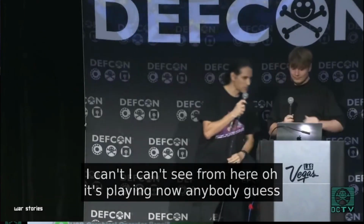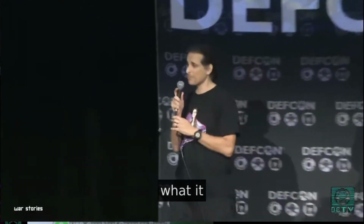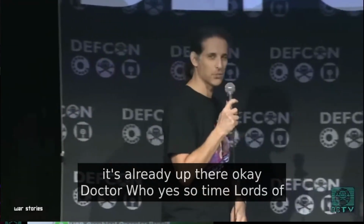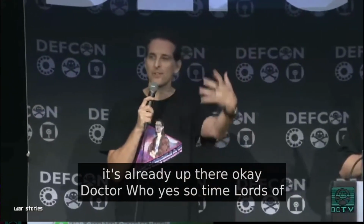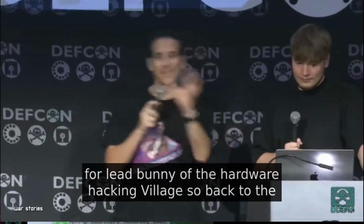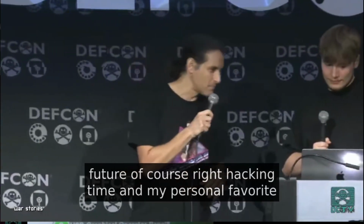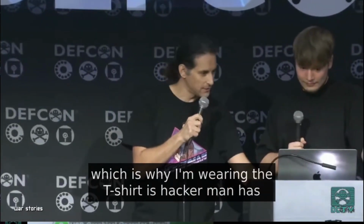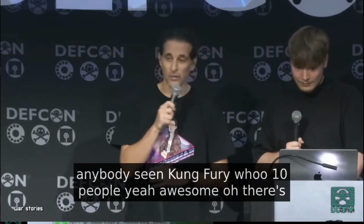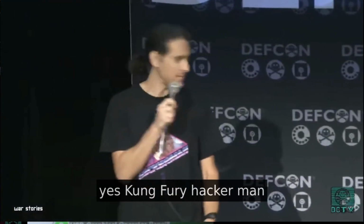The USRP also has a very low bit rate, so the analog to digital converter has an 8-bit sample rate. And we want higher samples. We want higher resolution so we can extract more signal. The USRP B210 has 12 bits, which is good, but it requires 70 megahertz, and we're just down at 400 kilohertz. But then I started looking, and there is something called an upconverter that we can get. The upconverter actually adds 125 megahertz to a signal as long as it's at least 100 kilohertz. So we're at 400 kilohertz.